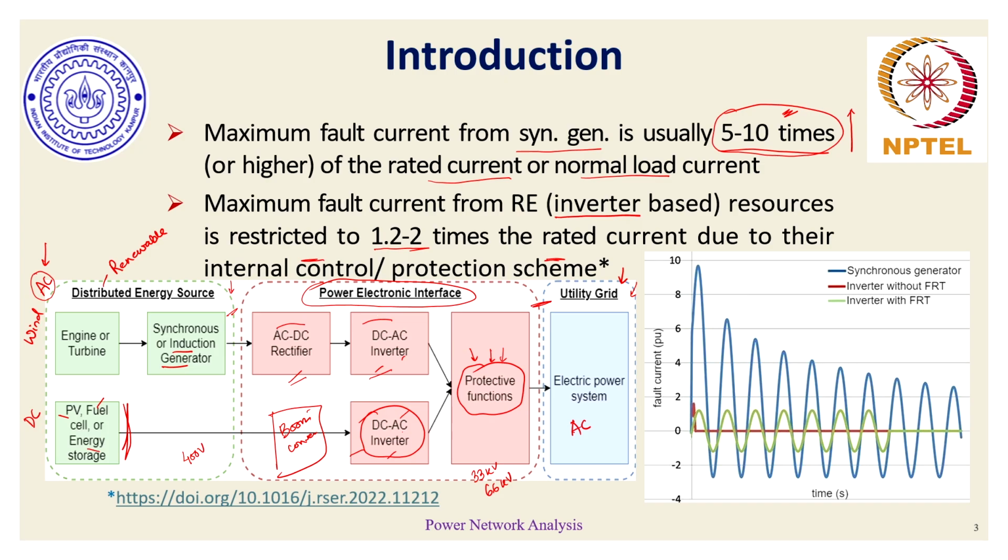synchronizing or connecting two non-synchronous devices, where here the frequency is not 50 hertz, whereas here the frequency is 50 hertz. So that's where we need an AC-DC converter or a DC-AC converter, again with voltage boost up or boost down capacities if required. So that's the essence of having this power electronic interface, which limits the fault current. And then there is also an aspect known as FRT, which in full is called fault ride-through capability. In literature, it is analogously termed LVRT, which stands for low voltage ride-through capability.